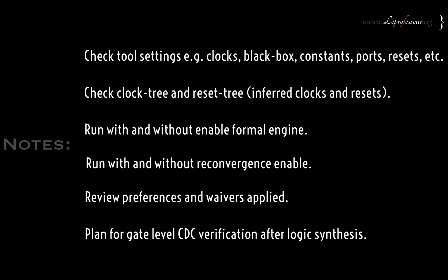Plan for the gate level CDC verification after logic synthesis, because what may happen is the logic synthesis tool may put certain logic which may violate the CDC. So plan in advance for the CDC when you are working on a full chip.